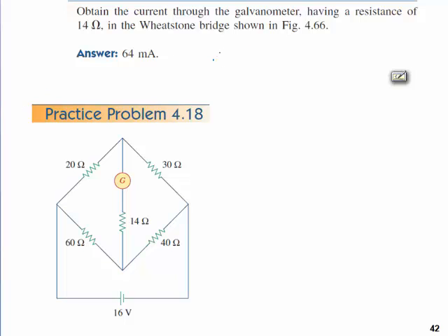So the first thing in Thevenin, this is the load right now between these terminals. So we want to know what is the current in this load. That's, for all intents and purposes, our load. So step 1 in Thevenin, what do we do? We take off the load. I'm a believer in redrawing circuits, but pretend the load is not there. But before I redraw the circuit, step 2, if we want to find our Thevenin, what do we do? You have to turn off the sources.